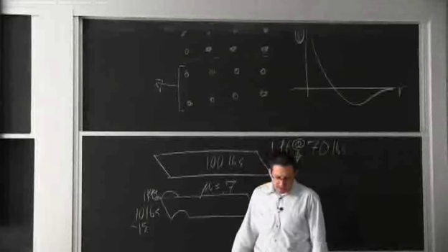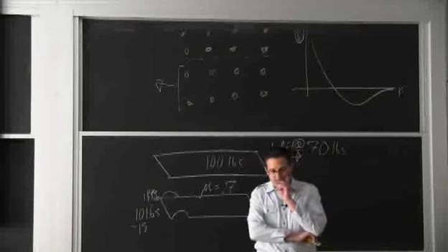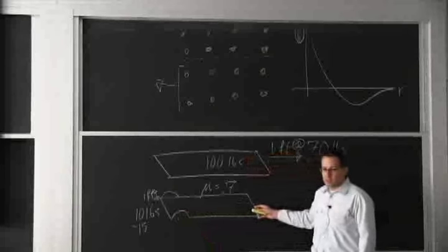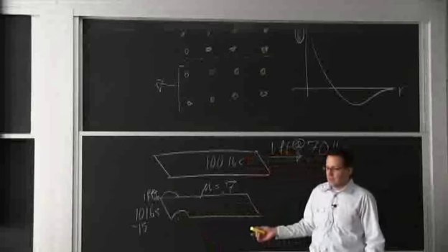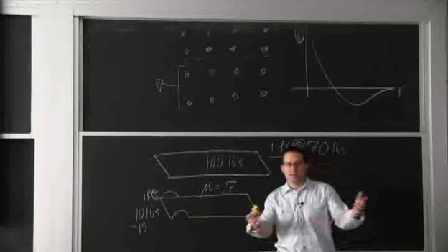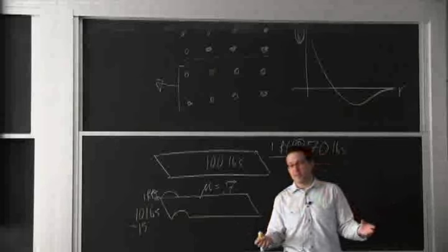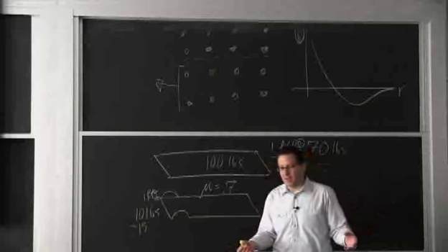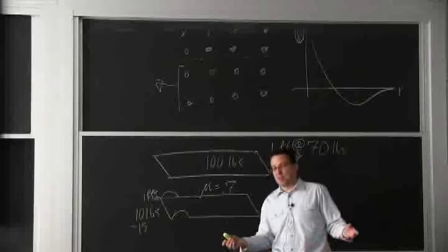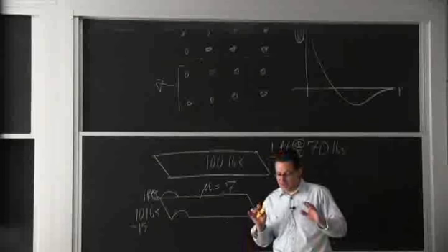The reason why plasticity is not reversible is that when I create that fold and propagate it in those crystals, I have to go through a lot of obstacles, and I'm going to create more obstacles. It's a war field. And after the war is over, you'll have to clean up if you want to come back the same way.